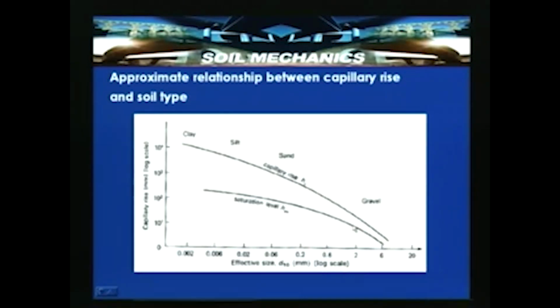This particular property is also considered wherever we want to prevent or arrest capillary action. When you do not want this capillary action to prevail, we use gravel or sandy soil materials as capillary cutoff materials. They can act as capillary cutoff layers to inhibit the soil from exhibiting this. This is particularly adopted for man-made structures, where a capillary cutoff is provided so that the soil does not remain saturated, because remaining saturated can change the properties of the soil.